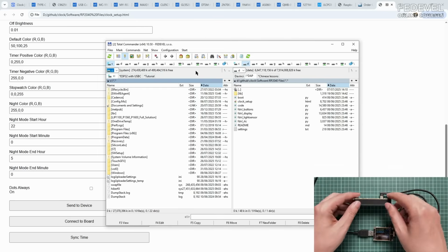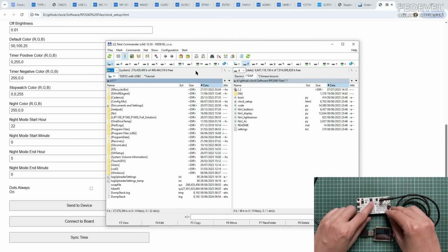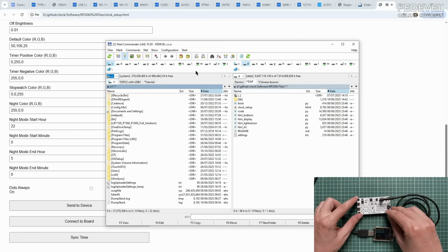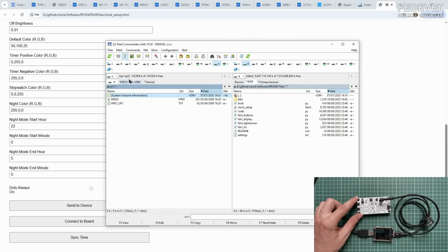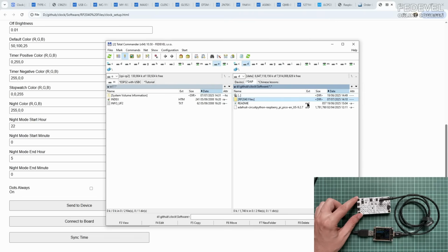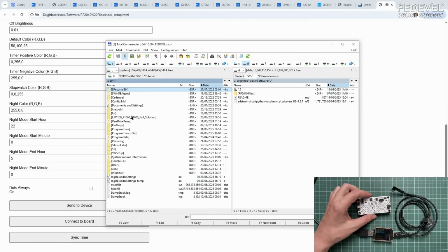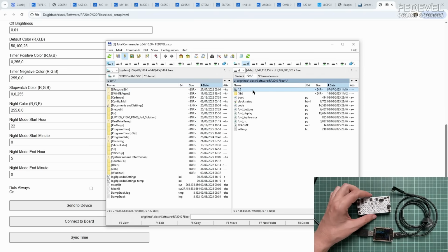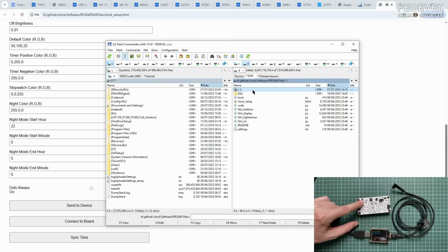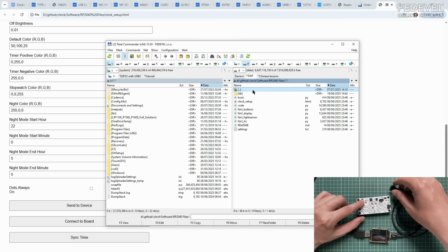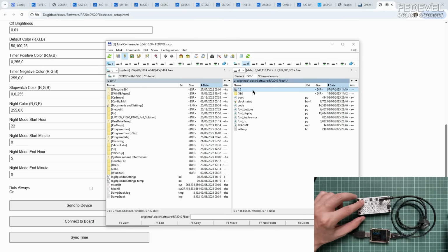Now, notice, as I said, there is no drive right now, but if you press the reset button twice, then you are back at the beginning and you can upload the firmware UF2 file. Or when you are connecting USB power and hold down this button, then you will be able to update the software for the clock.